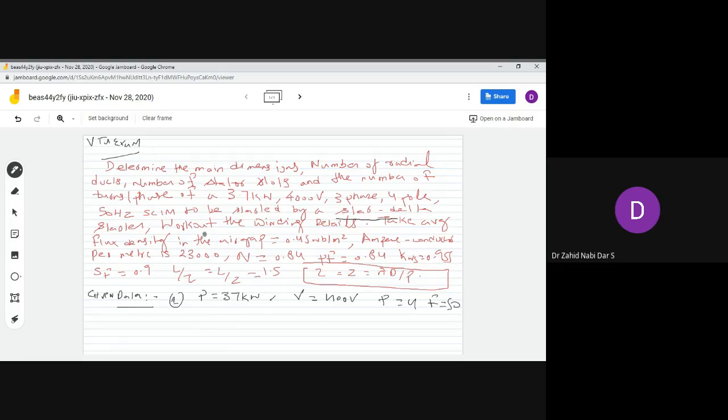Okay, so when you have to go for calculation of the voltage level, at the secondary side you notice it is started in delta, so in delta your V line is equal to V phase, so that is important. If it was delta star, then you had to divide by root 3.